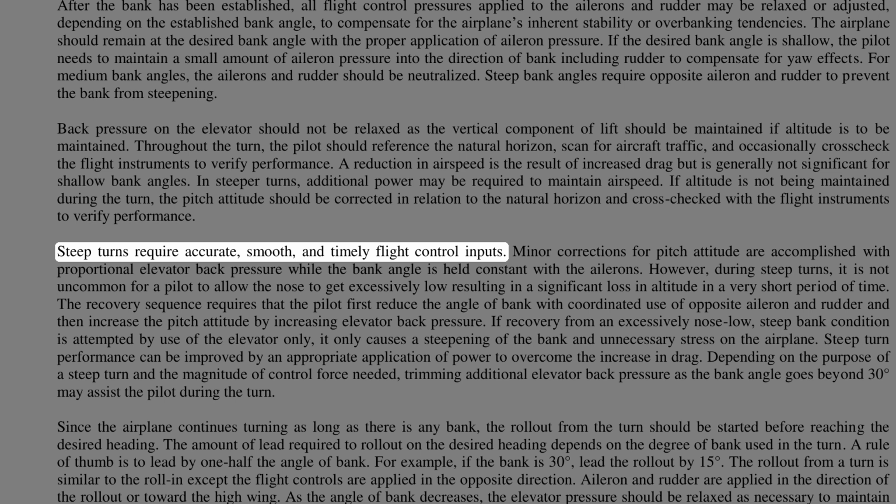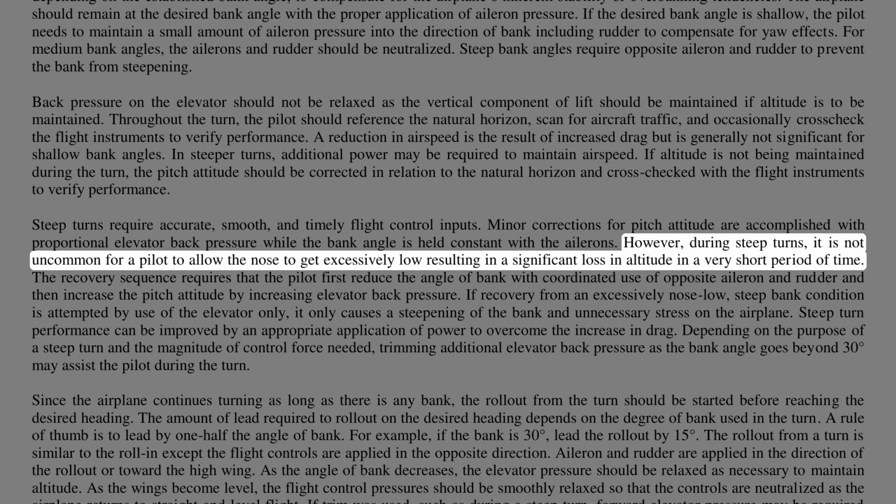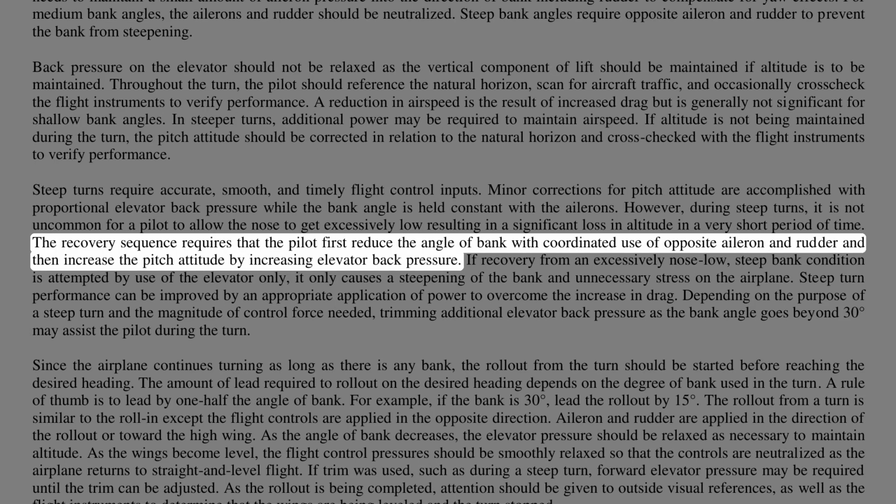Steep turns require accurate, smooth, and timely flight control inputs. Minor corrections for pitch attitude are accomplished with proportional elevator back pressure while the bank angle is held constant with the ailerons. However, during steep turns, it is not uncommon for a pilot to allow the nose to get excessively low, resulting in a significant loss in altitude in a very short period of time. The recovery sequence requires that the pilot first reduce the angle of bank with coordinated use of opposite aileron and rudder, and then increase the pitch attitude by increasing elevator back pressure.